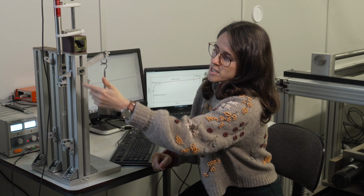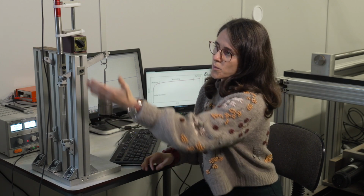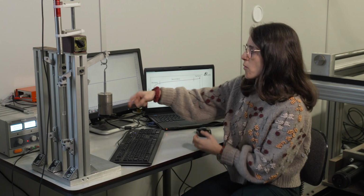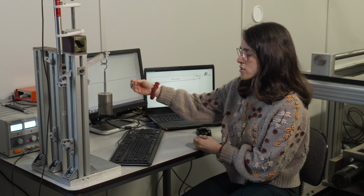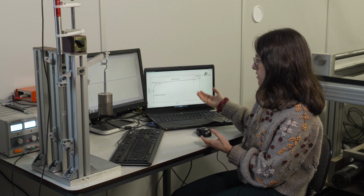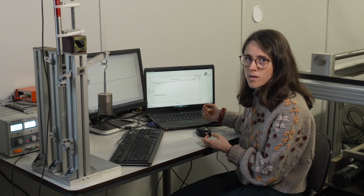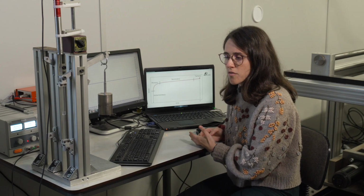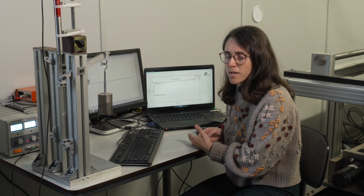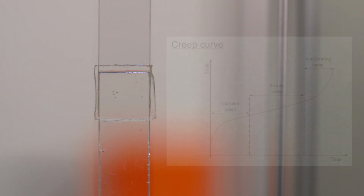To measure the displacements that we need for the final curve, we use an LVDT, a linear transducer, that is going to acquire the different voltage that is going to occur during the test, and in the end we can obtain the creep curve that we want, that is strain as a function of time. This particular device was developed for a project where we test PSAs for applications in electronics.